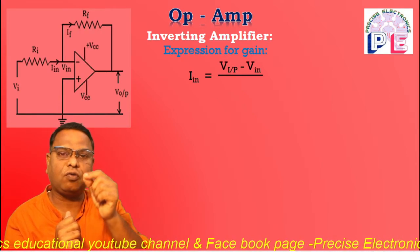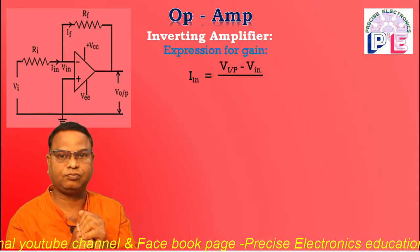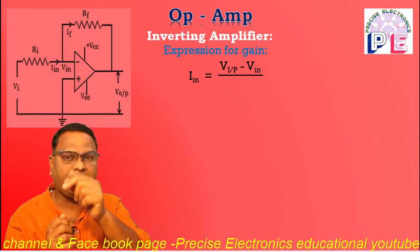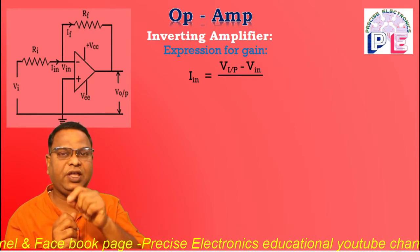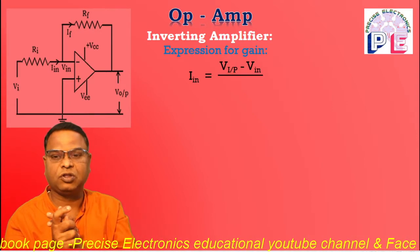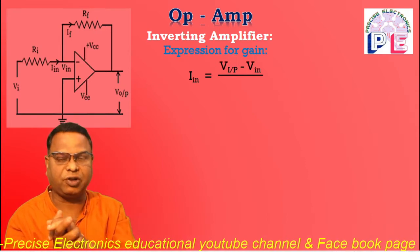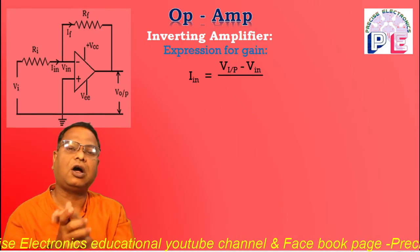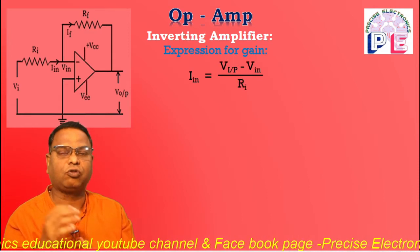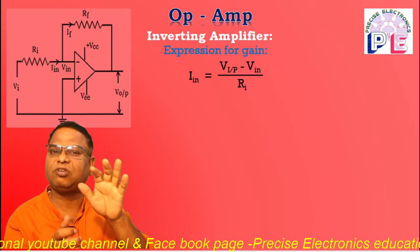That is a fraction of feedback potential developed across the actual inverting terminal. Vi is the input applied to input resistor, and Vin is the potential developed across the inverting terminal. That is (Vi minus Vin) upon Ri. Ri means the input resistance. So by using Ohm's law, we can find out the input current. That is our equation number 1.